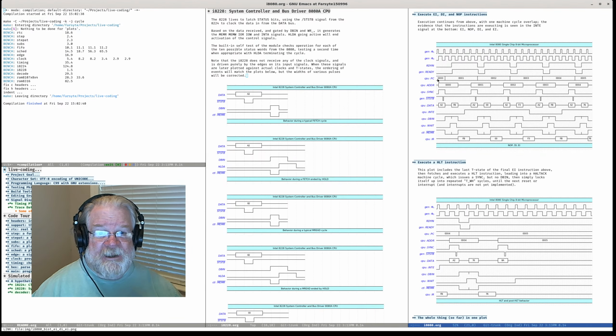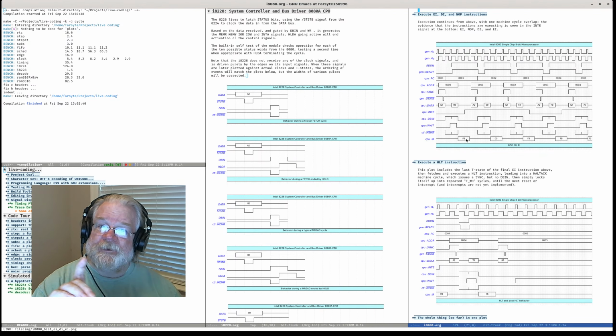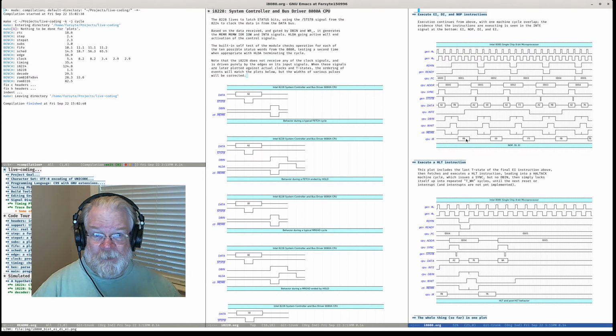So we've come out of reset and we fetch at 0. Here's the address bus, here's sync. There's the A2 saying this is an instruction fetch. Here's DBN and wait, and we get back the data from the ROM. And down here, we have also said we are going to expose the instruction register. This is not something that is program visible, but having it visible on the trace will help me debug any problems that go on. So we should see FB appearing on the data bus here, and we latch it into